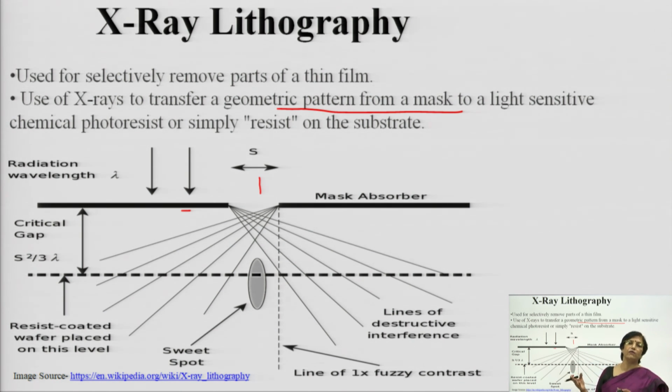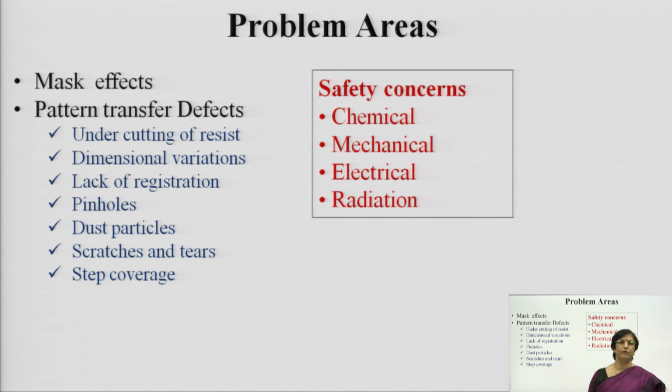The radiation is slightly harmful, so you have to take necessary precautions when the system is being used in the ambient surroundings. Similarly, the photoresist you are going to use should be a photosensitive material, sensitive to the X-rays. That is slightly an expensive affair, but apart from it, precision-wise they are very good, and they reproduce the output very effectively.